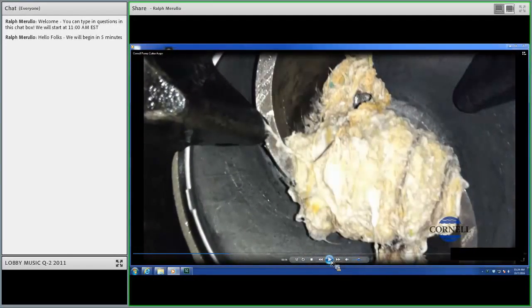So this is the problem. What this is, is all those wipes, all those baby wipes and all that kind of stuff. People throw them down the toilet, and they end up right at the suction side of the pump. And what happens is they call this ragging out, okay? Now, remember, we explained that mechanical seal, it's got to be lubricated by liquid. Well, this fibrous material will collect in the seal chamber and starve the seal of fluid at the primary seal. That's the problem, right?